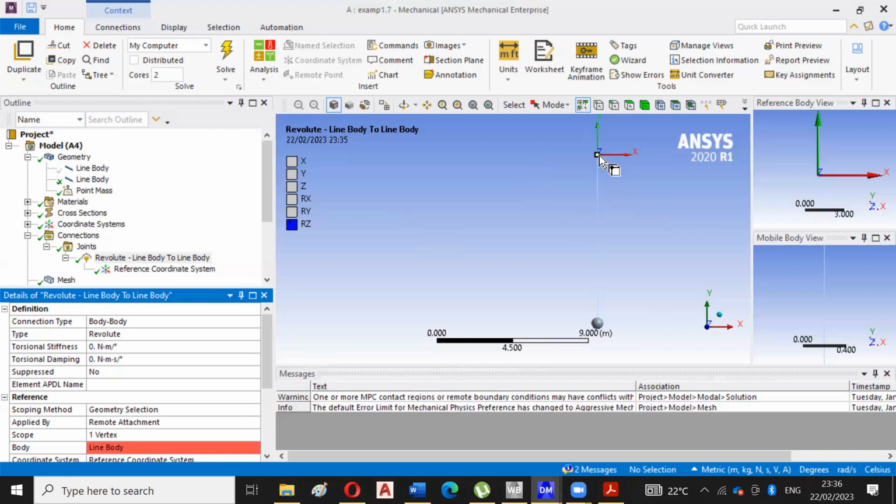So, to clearly specify that this point is selected on different beams, we must hide one body at a time and then make it visible, for foolproof selection of the same point on two different bodies.